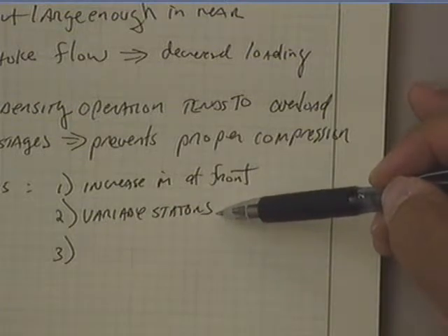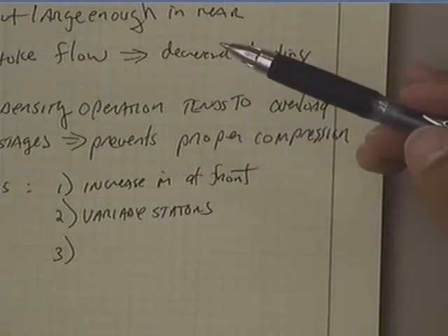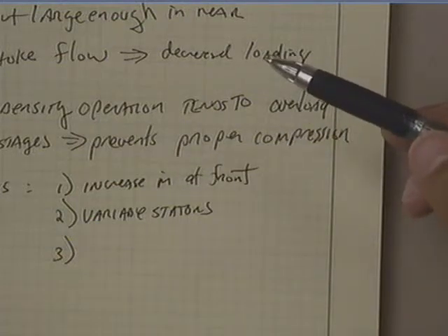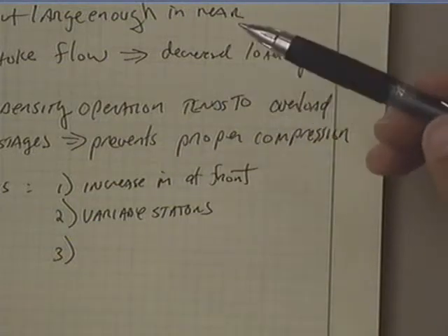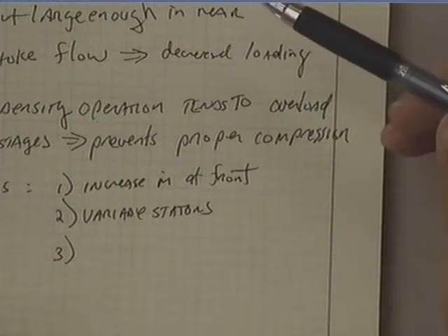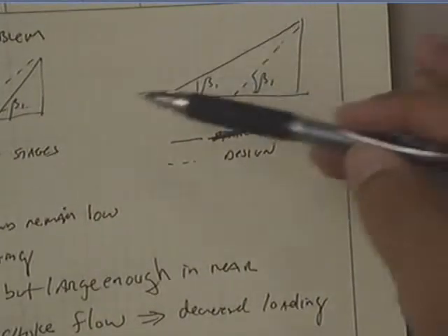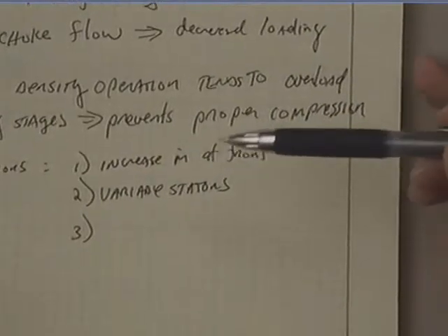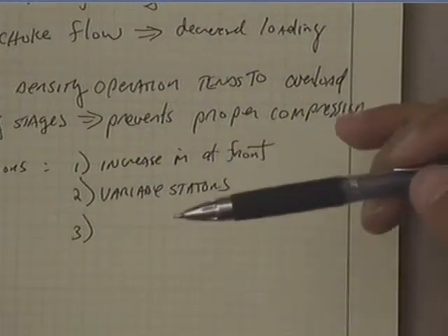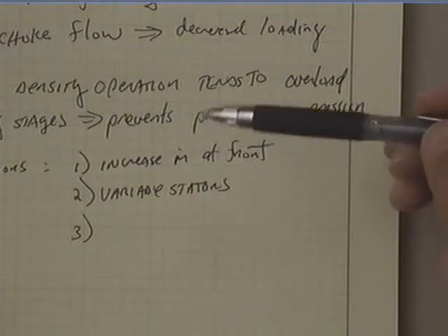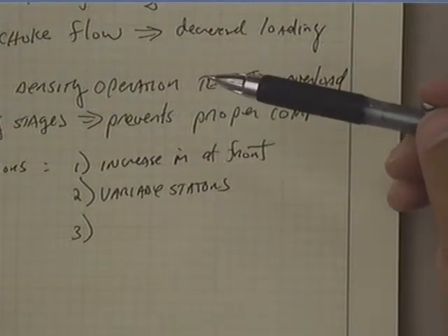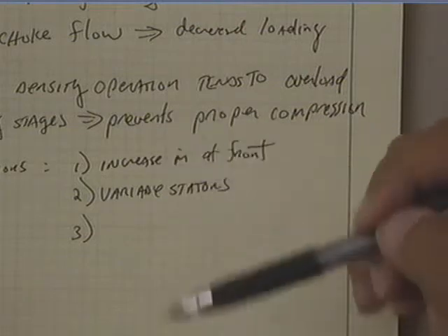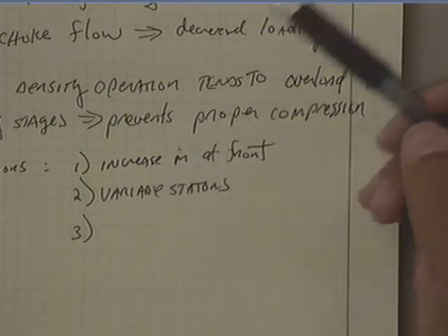Now, instead of having a static airfoil design through the compressor, if I have the ability to change the air angle, which effectively means I'm going to change beta by changing the stator angles, so I'm changing the relative angles going into the rotor, I can overcome this starting problem. And then as this spool speeds up and I pump more and get more MDOT, I can control that.